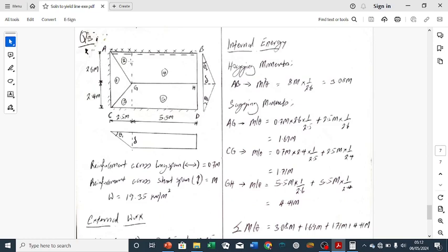The yield line pattern is such that you can see the whole of this plate. First of all, this is the hogging yield line inside AB that is continuous. You only have hogging yield line on the continuous edge. So this is the hogging yield line. And after that, this is a sagging yield line. This AG and CG and GH are the sagging yield lines, while this dotted vertical line are just to divide this into triangles and rectangles. We don't want to start dealing with trapezium.